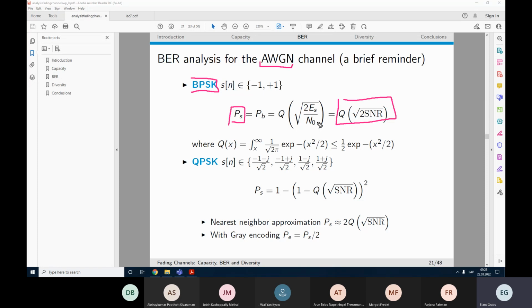So this was depending on the distance between signals. For example, if we talk about binary phase shift keying, then we have real signal, for example, +1, and real signal -1. And the phase difference is pi. And there is some distance between signals, which can be calculated as the maximum signal minus minimum. So +1 minus -1. And that's the factor of 2 coming into this expression.